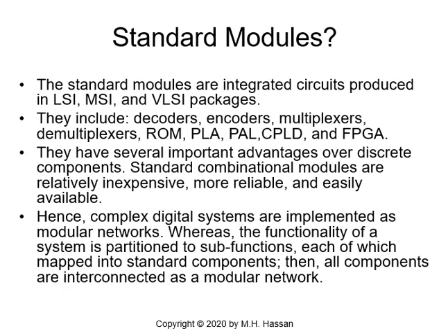They have several advantages over discrete components. Standard combinational modules are relatively inexpensive, more reliable, easily available. They are smaller in size, they consume less energy if you replace gates with them, and hence complex digital systems are implemented as modular networks, whereas the functionality of the system is partitioned into sub-functions, each of which is mapped into standard components.